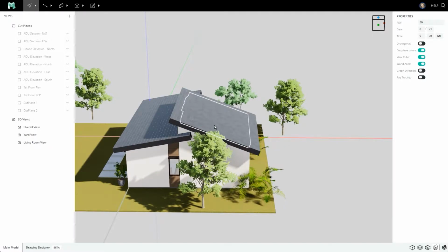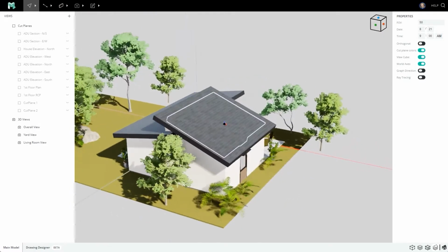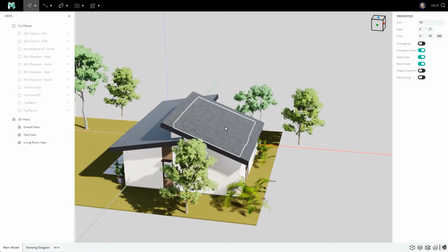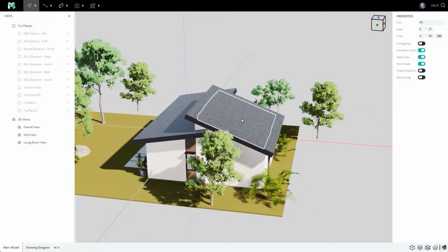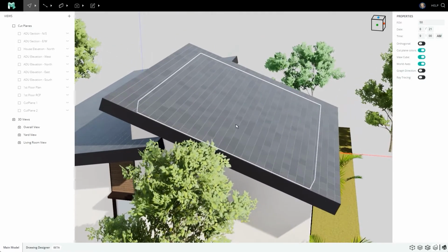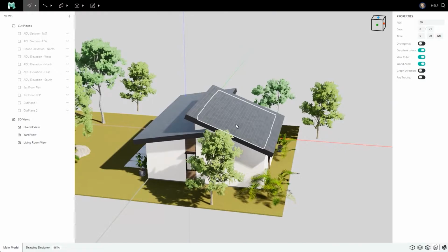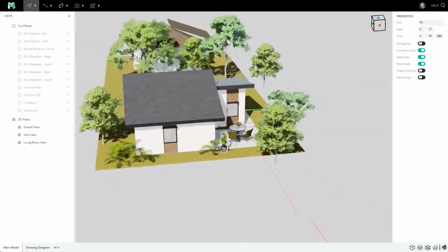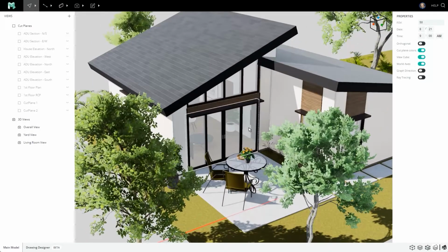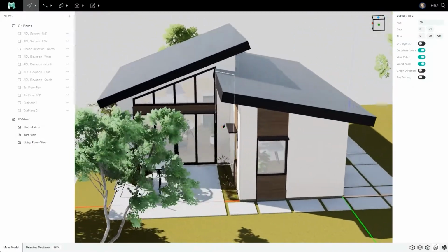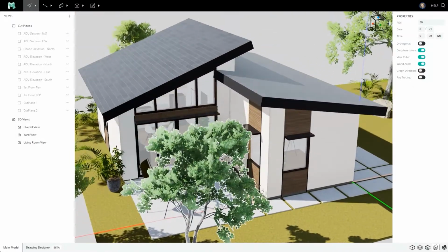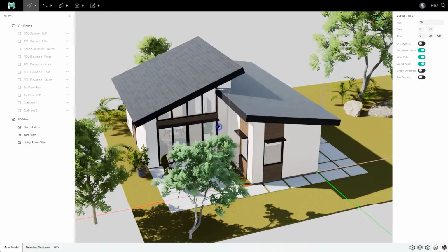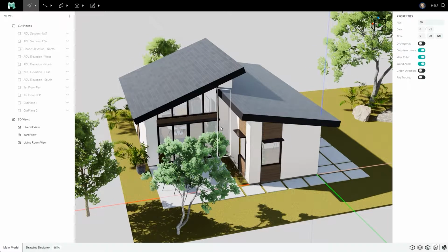First, getting around your project involves orbiting, which means right-clicking in the scene and moving your mouse on the table, as well as panning, which means pressing your middle mouse wheel in like it's a button and moving your mouse on the table, and zooming, which means scrolling your mouse wheel up to zoom forward and down to zoom backward. With the combination of these three camera behaviors, you can travel around your scene and view your building from all sorts of directions. Orbit, pan, and zoom are the three most commonly executed commands in Modumate.